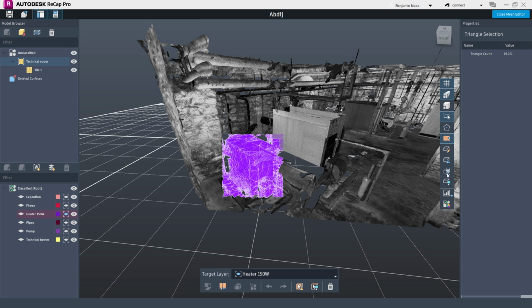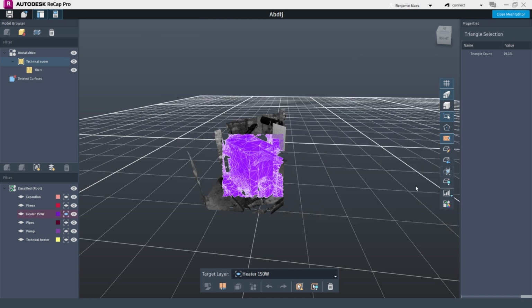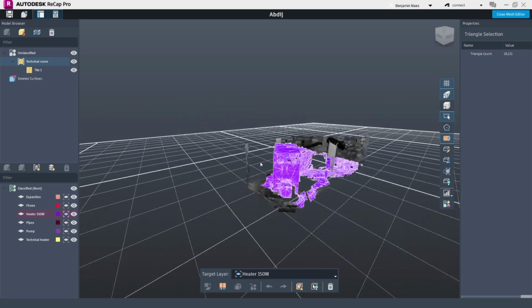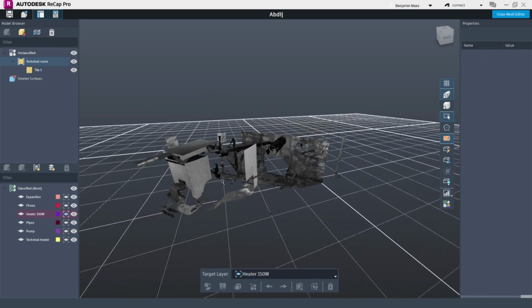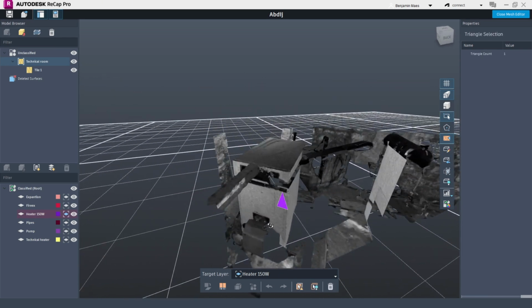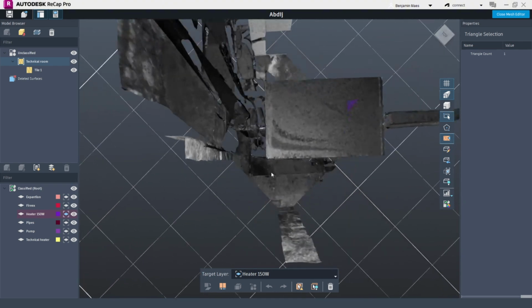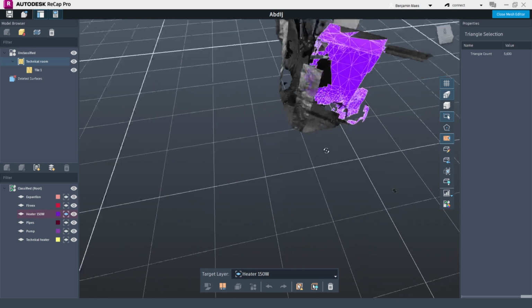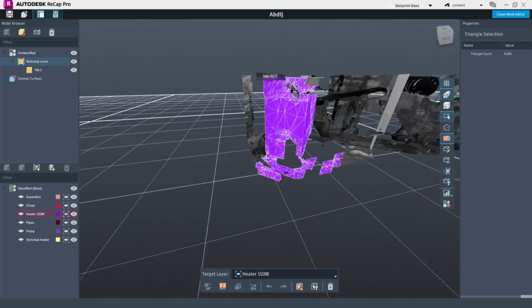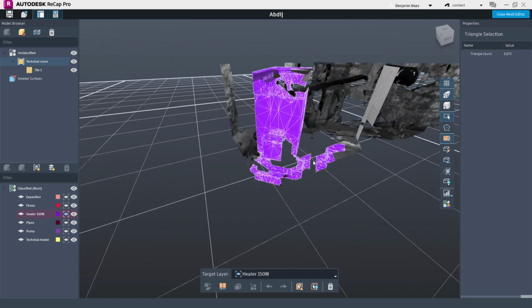And then you say here set limit box to selection extents. Now I selected a lot of things, but I only want to have this thing. So the heater I selected, going around, and these things I don't need. So you can deselect.